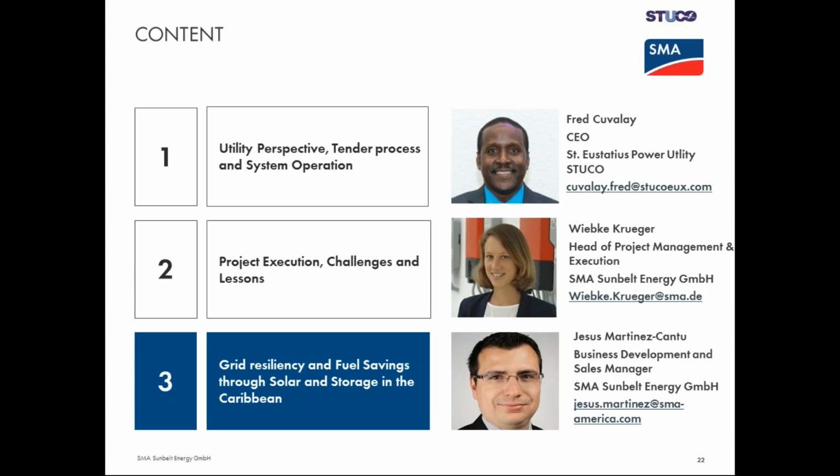With the grid forming inverters in phase 2, a PV system can supply not a home but the whole island, and you can shut the generators down and it continues to supply the island. It then provides all the functionalities of a power system, generating voltage and frequency for the entire island. That's the grid forming part, which is not possible with conventional PV inverters that you would find at your home.